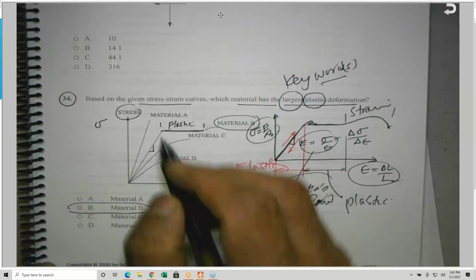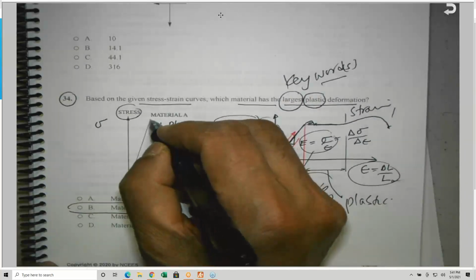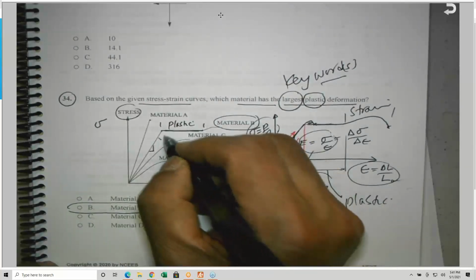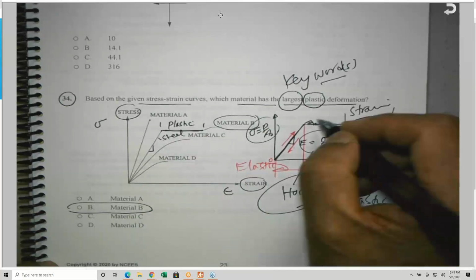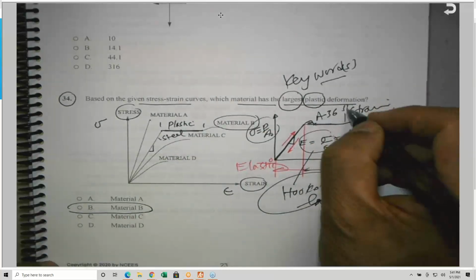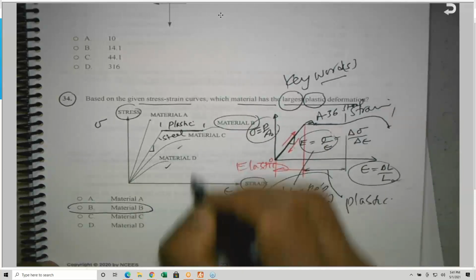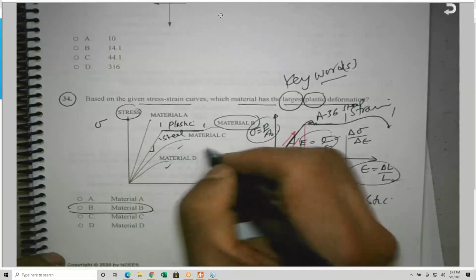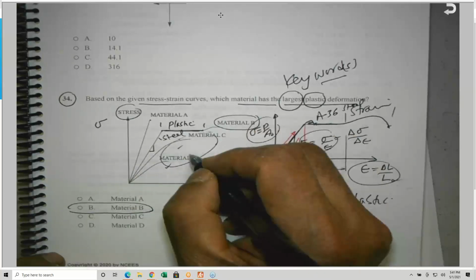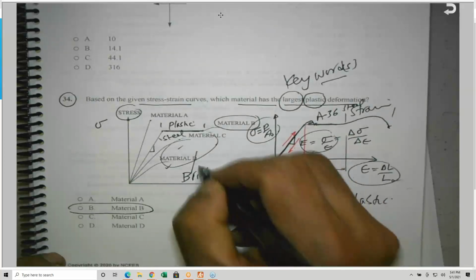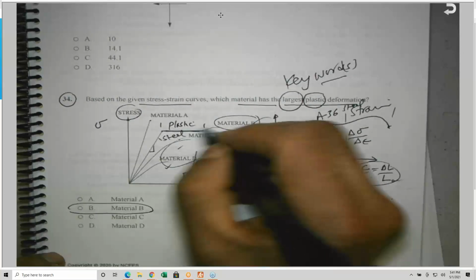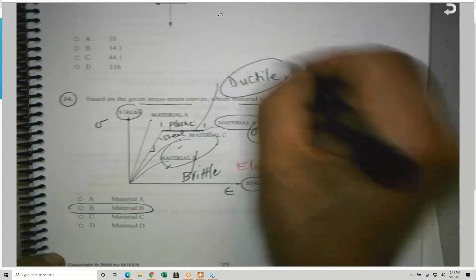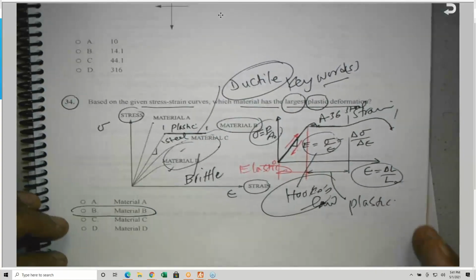So this material here goes straight and it fails up to here. This here is non-linear, by the way. Steel is a very good example, like this one here. This is for A36 steel. This material and this material here, this is like concrete, okay? It has a non-linear curve, so it's a brittle material, like concrete, as we're going to see in the materials section. Steel is a ductile material, or ductile as the British pronounce it. So we need to pay attention to these things, okay?